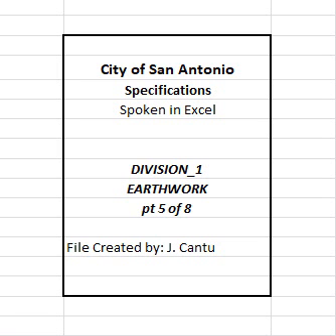Scarify and loosen the unpaved surface areas, except rock, to a depth of at least 6 inches, unless otherwise shown on the plans. Bench slopes before placing material. Begin placement of material at the toe of slopes. Do not place trees, stumps, roots, vegetation, or other objectionable material in the embankment. Simultaneously recompact scarified material with the placed embankment material. Do not exceed the layer depth specified in section 107(3)d, compaction methods.